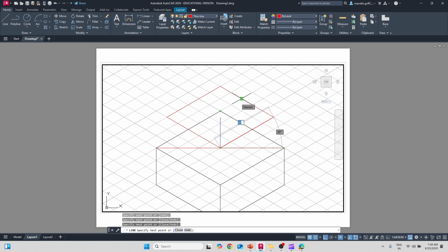Okay. After this, what we need to do is go for the line command again, right? Then again, you go for thin line. That's fine. See, from this, I'll switch off F9. Here, what is the midpoint? If it is 50, then 25 will be the midpoint. Then again, from this midpoint, right? 25. Then again from the top also midpoint. See, from this to here, that is midpoint. Then again from this also midpoint, right? See, this one, the midpoint.